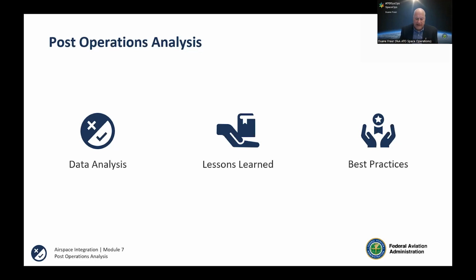So we'll block the airspace, we'll block that same 10⁻⁶ hazard area, and we'll move aircraft around that and very tactically, very dynamically manage. We have some suborbital locations where an operator will have, let's say, a 6-hour launch opportunity, but the airspace is only blocked for 30 to 45 minutes because we're so capable of tactically managing that airspace.